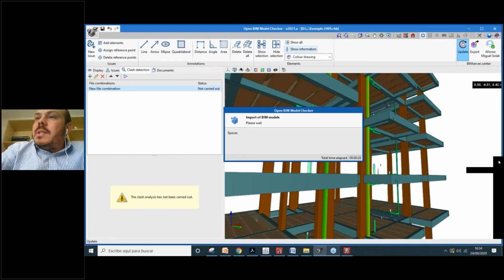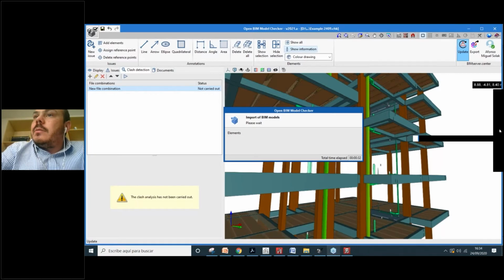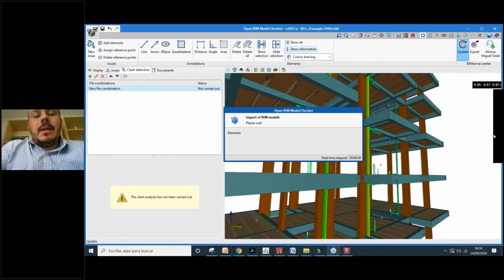Okay, let me see, we have a little question here. Just a second. Can we delete items from the IFC file to streamline the IFC file? Yeah, Paul, we can delete all the information that is created by us. So my own information I can change, okay?